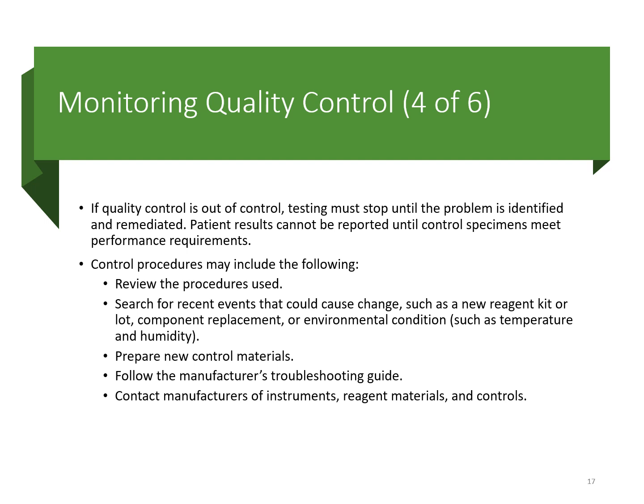Maybe you're 2 or 3 days away from a required maintenance schedule of something that needs to be changed on the machine. Maybe the light bulb is due to be changed in 2 or 3 days, so maybe you want to do that a little early. So there are some things that you should do to look at, what's my next step? What do I need to do? What do I need to look at? So it's a troubleshooting process once you start seeing that your QC values are giving you an indication that something's wrong.